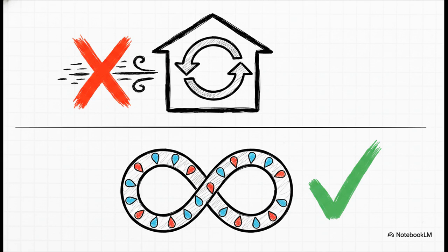Second myth: air conditioners need their refrigerant refilled every year. Busted again, because the refrigeration cycle is a totally closed loop. The refrigerant is literally never used up. You should only ever need a recharge if your system has a physical leak.